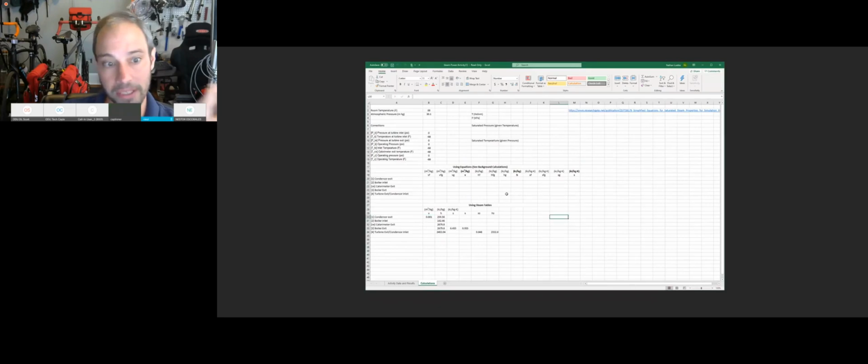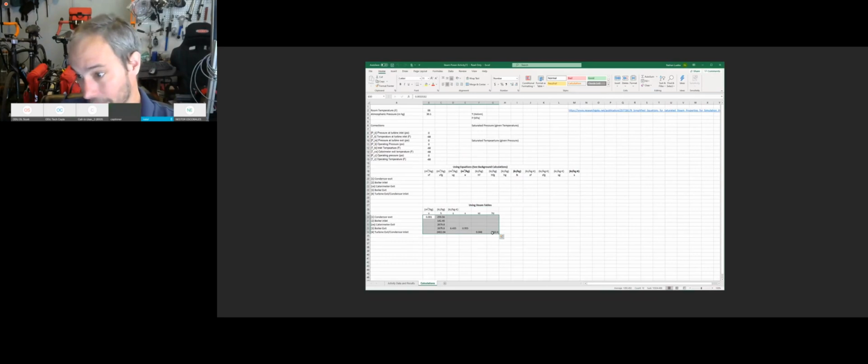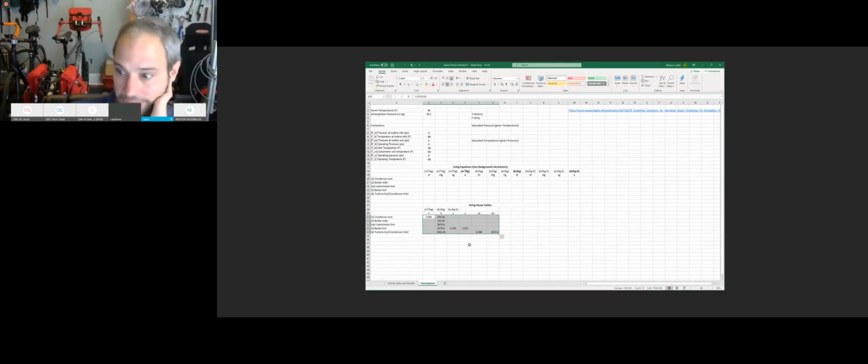It's not even that involved actually, because all these enthalpies here, these values, use steam table information down here that I'm highlighting. I read these values off the steam table. So no matter what temperature and pressure you put in on the upstream side, these are going to be correct. It's not an easy equation for it. I finally got my spreadsheet to do that, but it's way more complex and it's not cleaned up and ready for prime time yet.